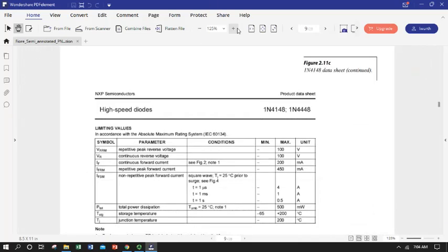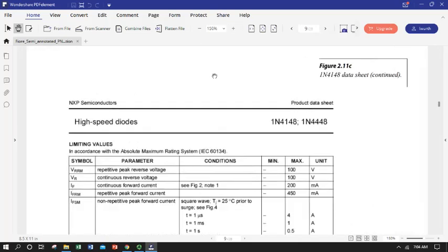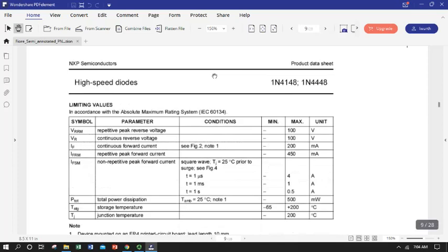So that's been calibrated for you. If you want to understand what capacitance your diode is going to add to a circuit, because maybe you're looking at it as an AC component, you're calculating resonance or something, and you want to make sure you understand what capacitance has been added by adding a diode, you can pick it right off the graph in terms of your reverse bias, your DC reverse bias.